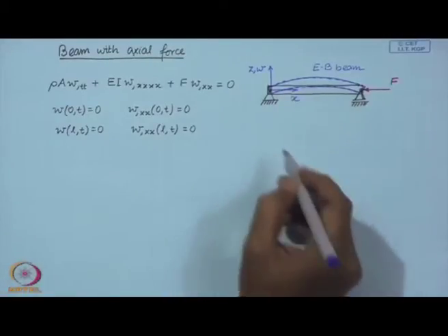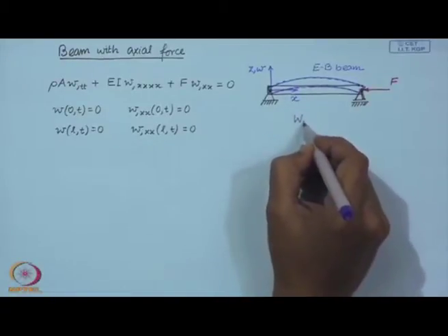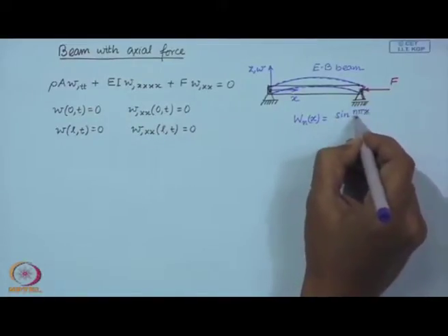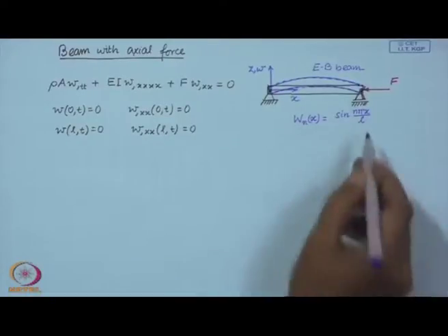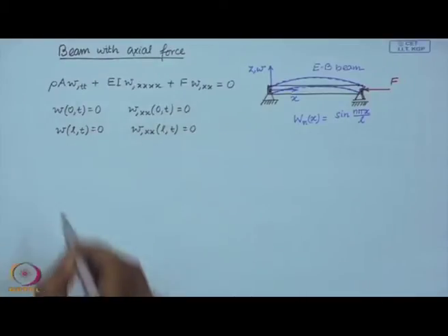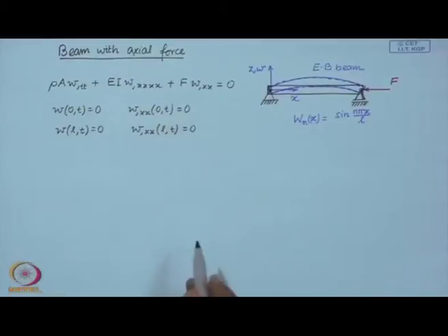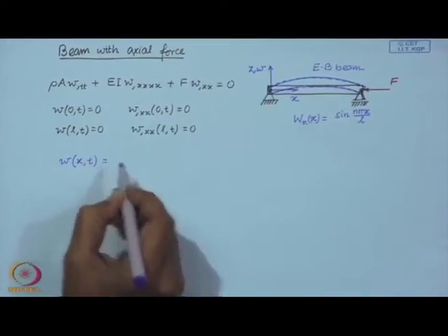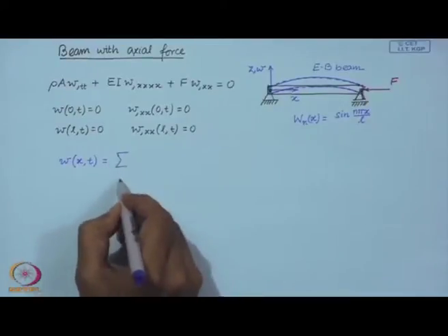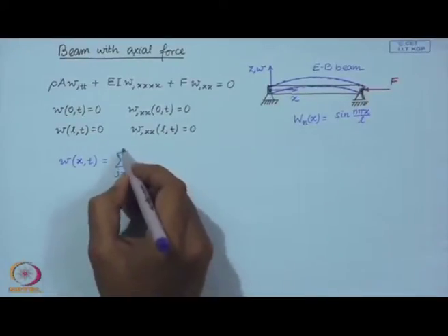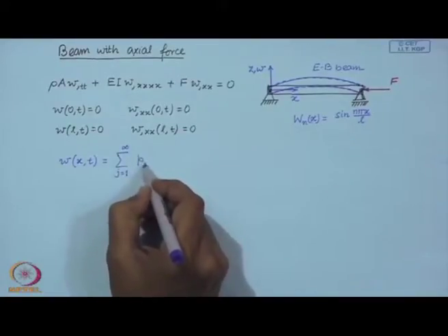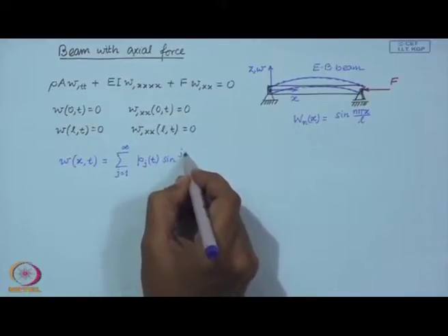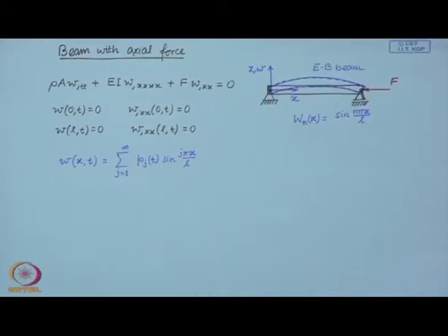We know that the eigenfunctions of a simply supported beam are given by sin n pi x over L. So, let us construct the solution of this dynamics with axial force as an expansion in this form.